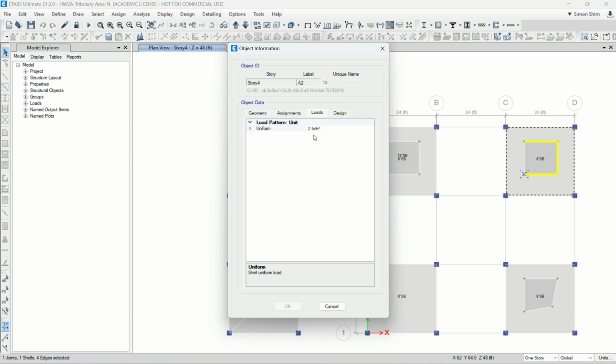So in this case I have a big area and I have another small area. It's duplicated, but they recognize it internally, so they don't add the weight twice, right? But they recognize the area load from here and here, so they add it together.